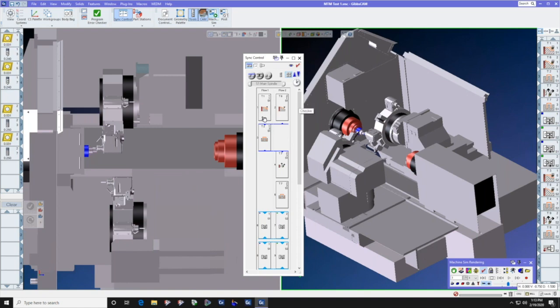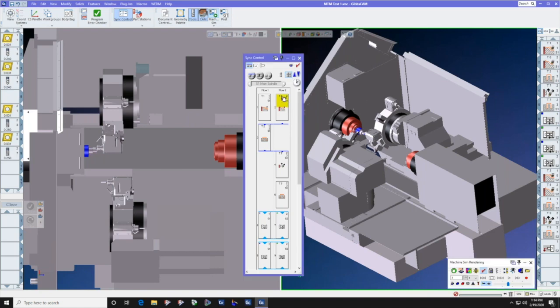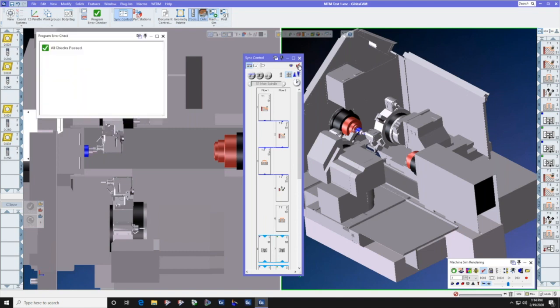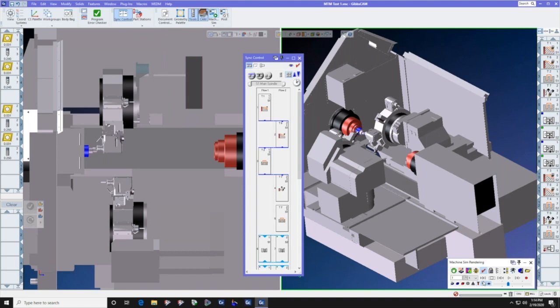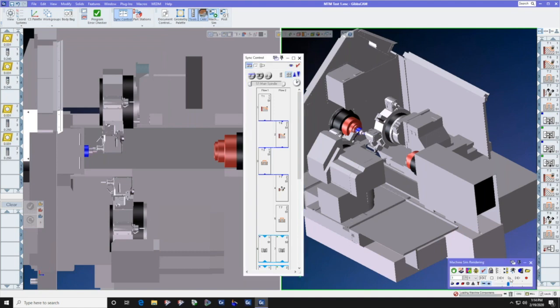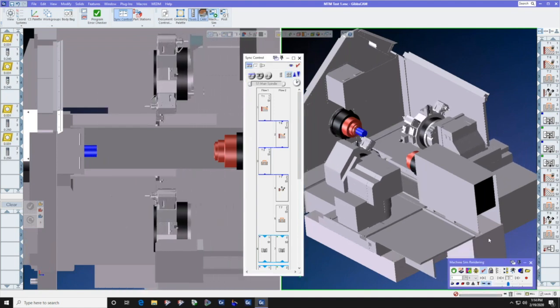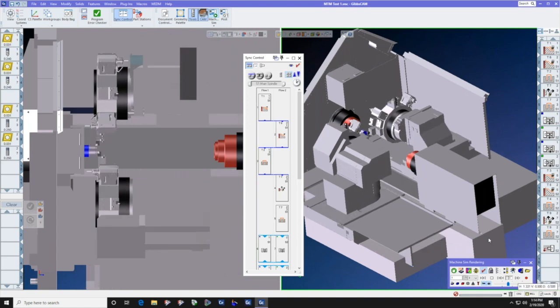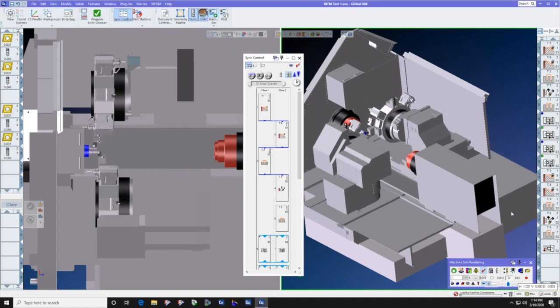We're going to put the synchronization back in and tell the top of Op2 to wait until the end of Op1 to do its job. And we use the program checker to tell us that all checks have passed. We'll do a quick run back to the beginning of the program, and we'll see that now everything is okay.